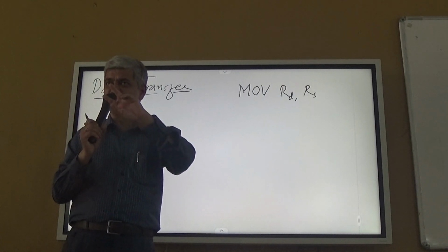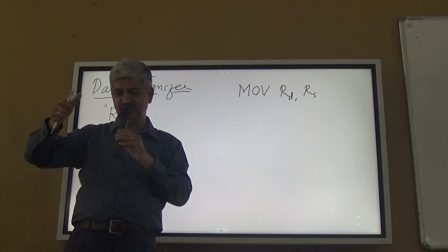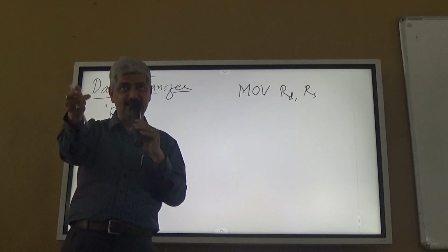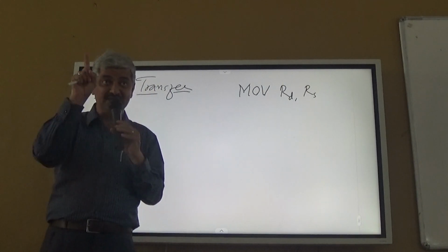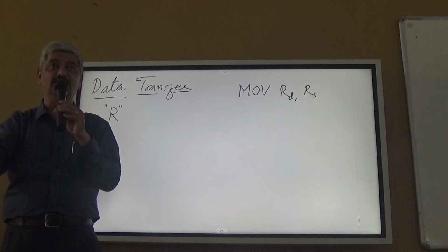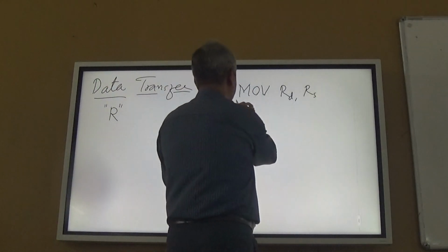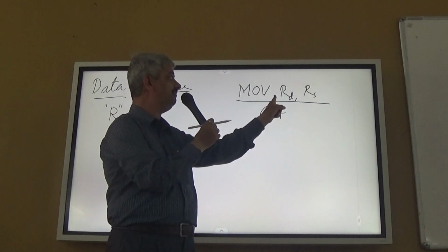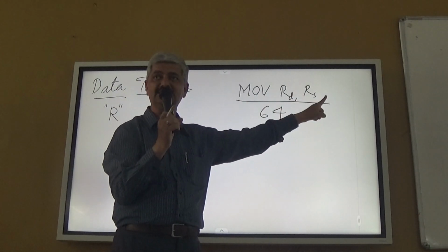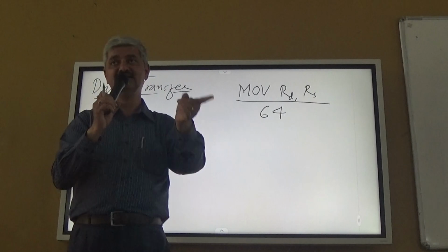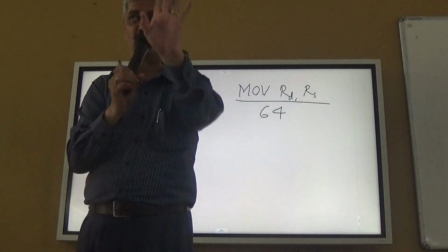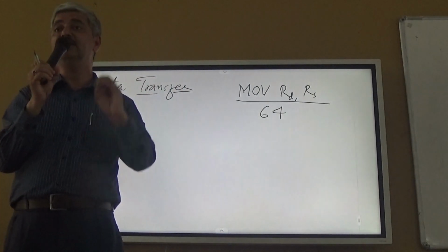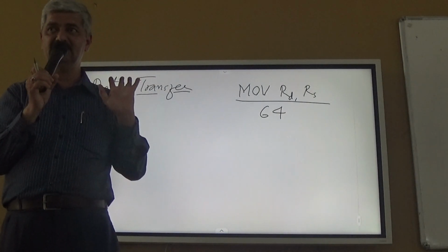Because of the arrangement of opcodes, two dummy instructions like MOV A, A and MOV B, B are also there. But MOV M, M is not an instruction. It is used for HALT. So there are 64 such possibilities with a 3-bit value of RD and a 3-bit value of RS. Of these 64 possibilities, 63 are move instructions and 1 is HALT, right? So 63 inter-register movements including M are possible, right?